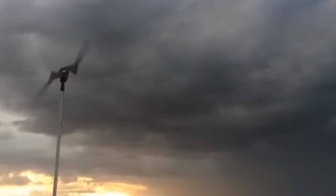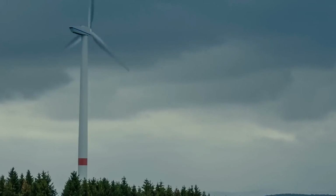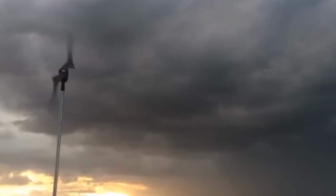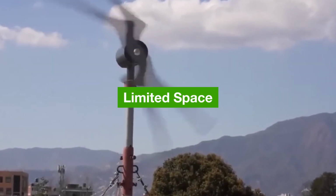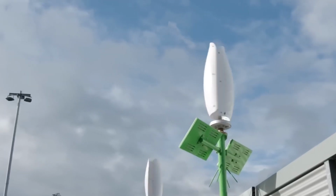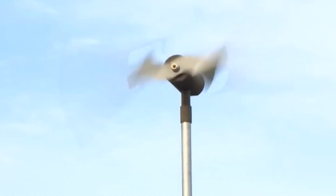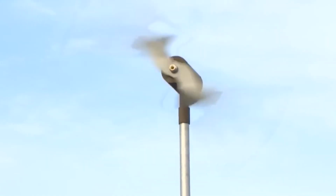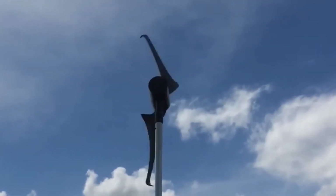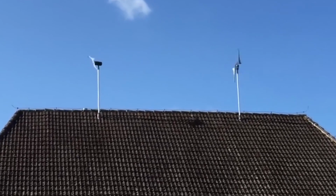Rooftop. Small wind turbines have some of the same disadvantages as larger wind turbines, but they also have some additional disadvantages, including limited space. Rooftop small wind turbines are limited by the amount of space available on a roof. This can make it difficult to find a location that is exposed to enough wind to generate a significant amount of electricity. Weight. Rooftop small wind turbines can be heavy, which can put stress on a roof. It is important to make sure that your roof is strong enough to support the weight of a wind turbine before installing one.